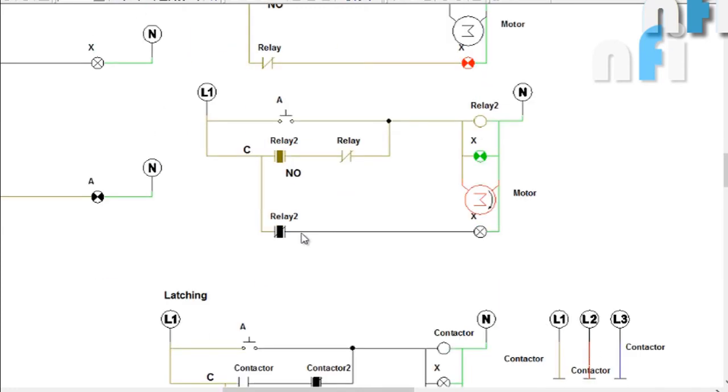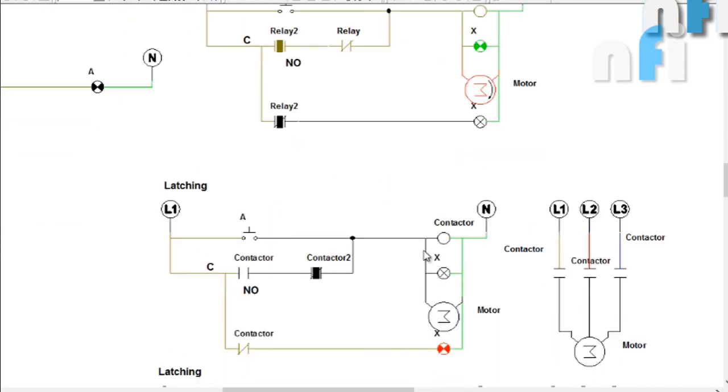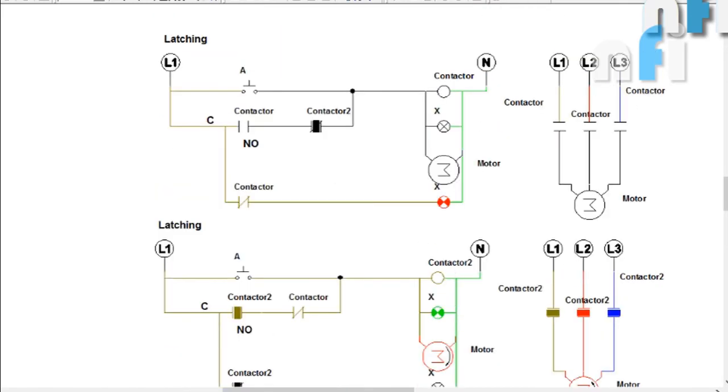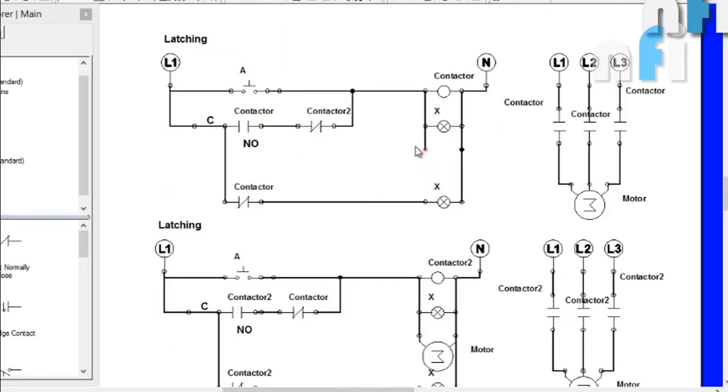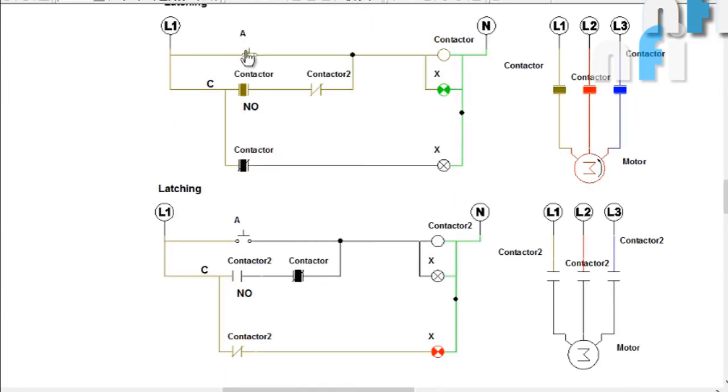Alright. So in here we have just a single phase motor, so we have connected in parallel. Here it's a 3-phase motor. Oops, why do I have this connected? I don't need this here. Sorry. Here it's a 3-phase motor, so we have to connect like this, because 3-phase requires 3 contacts, so L1, L2, L3. That's how it is being done.